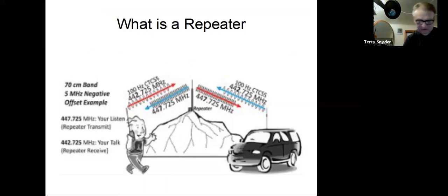And some people have them turned up a little bit too high on their repeaters and you can hear them. And that is the tone when you program a repeater into your radio, that you have to have that tone there, and here's what it's for. It triggers a relay in the repeater, essentially, and lets it go into the retransmit mode. So you have to have that tone coming in.